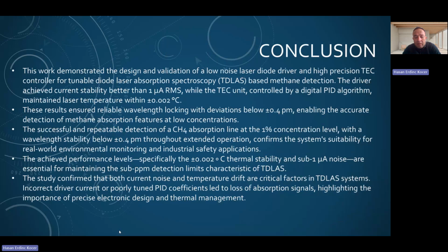As we can conclude this study, we can say that this work demonstrates the design and validation of a low noise laser diode driver and high precision TEC controller for tunable diode laser absorption spectroscopy based methane detection. These results ensured reliable wavelength locking with deviations below minus and plus 0.4 pm, enabling the accurate detection of methane absorption